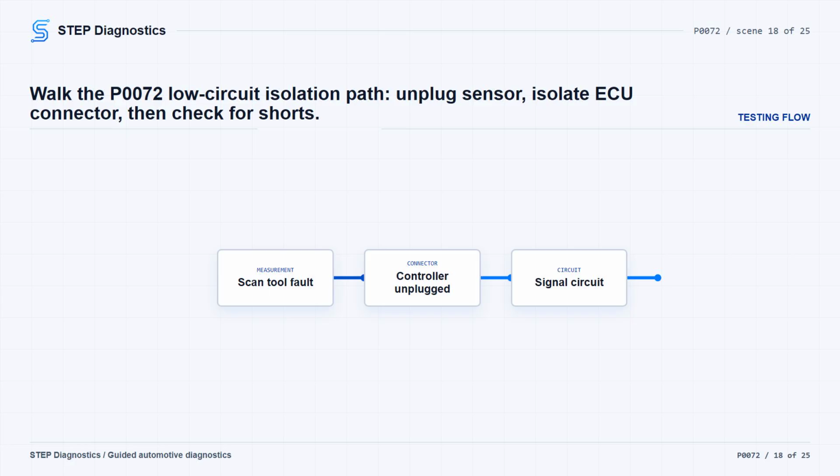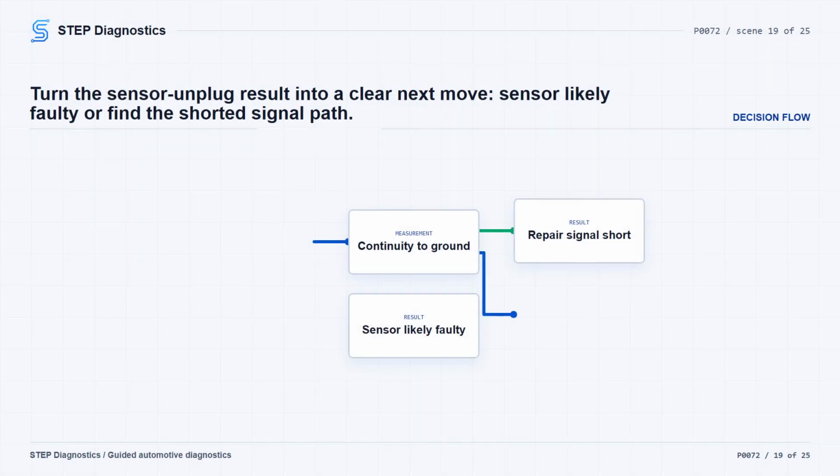as needed and check the temperature sensor signal circuit for high resistance and short to ground. To check the temperature sensor side, move the test lead over and back, probe the temperature sensor ground circuit at the temperature sensor harness connector. For an active circuit low fault, disconnect the temperature sensor connector while watching the scan tool for the circuit high fault to become active.